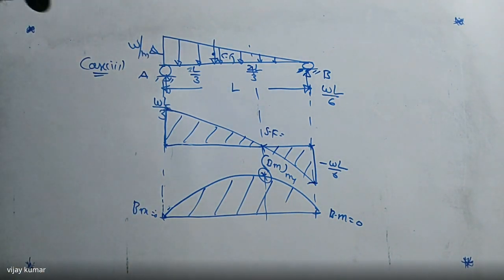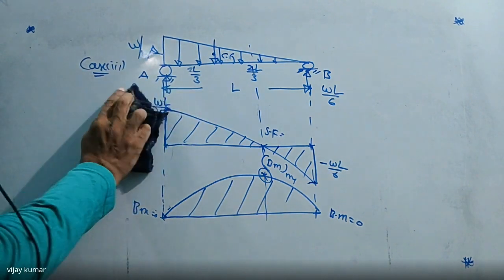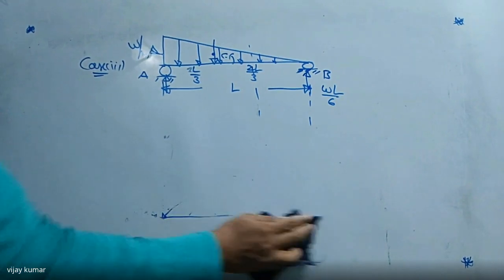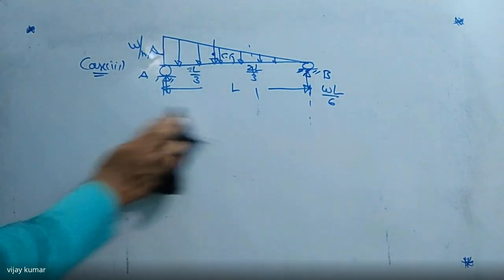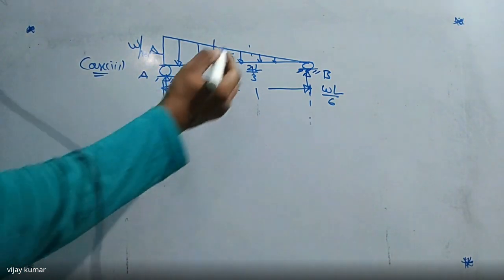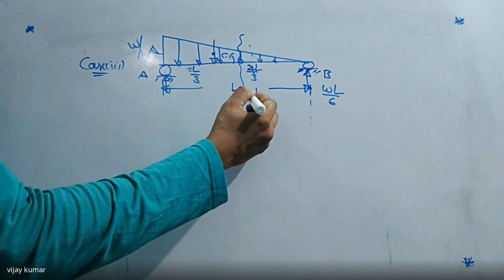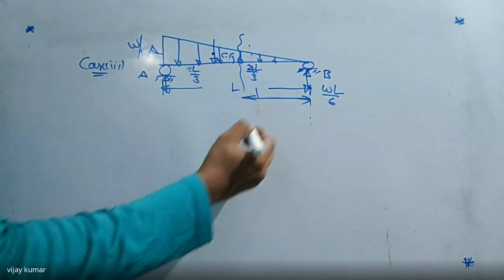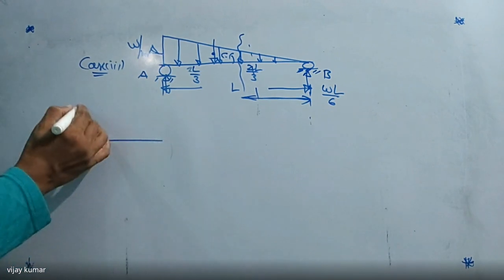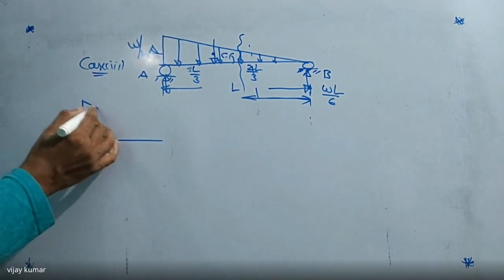First of all, listen carefully. For this beam, I'm going to explain where the shear is zero, how to find maximum shear and how to find maximum bending moment. You got my point? So as the general procedure, I'm going to cut this beam into two parts. I'm taking this one, the right hand side.